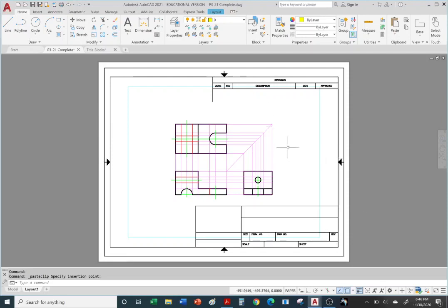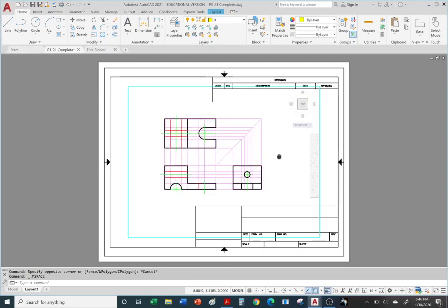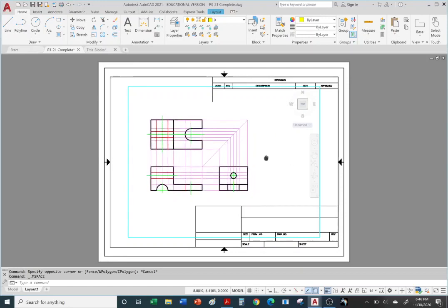Okay, so now let me go back to my viewport. Double click inside the viewport, and let me go ahead and center my views. It's a lot better. Yeah, I'm missing my dimensions. I can always spread out the views to make more room for my spacing here, and I can double click outside to exit the viewport. Okay, so now let's say we wanted to print our layout with title block and border.